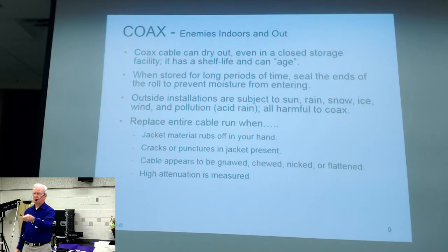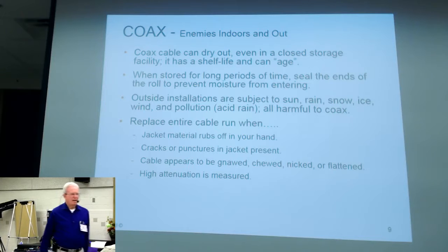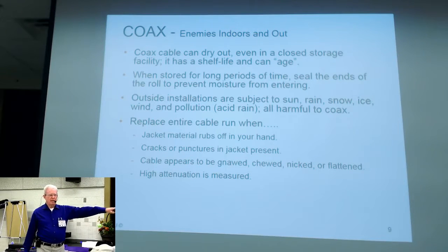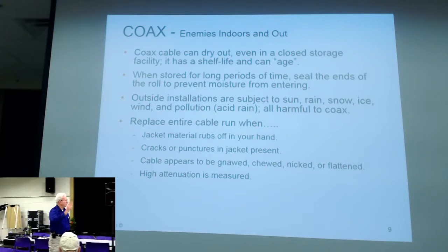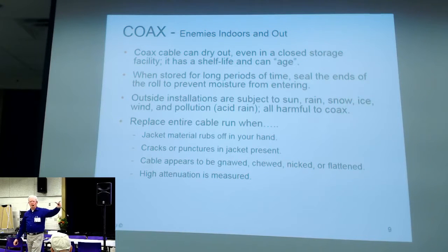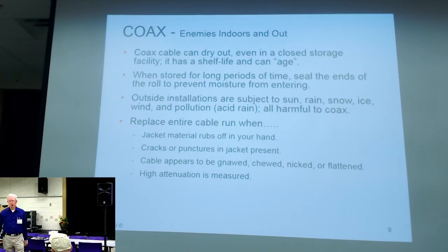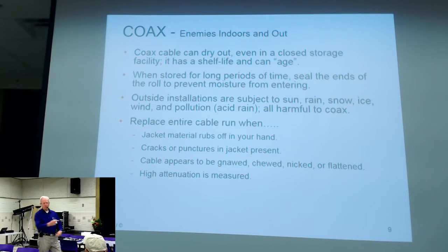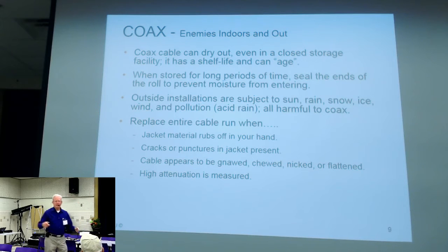Exactly. Oh yeah, this is no longer 50 ohms, John. This is what I do every year, guys. I actually unhook my antenna and put a Bird wattmeter outside with a dummy load, and then I go inside and put another Bird wattmeter, and I put 100 watts in, and then I go outside and read the output, and I calculate the dB loss of the cable, and that way I keep up on it.